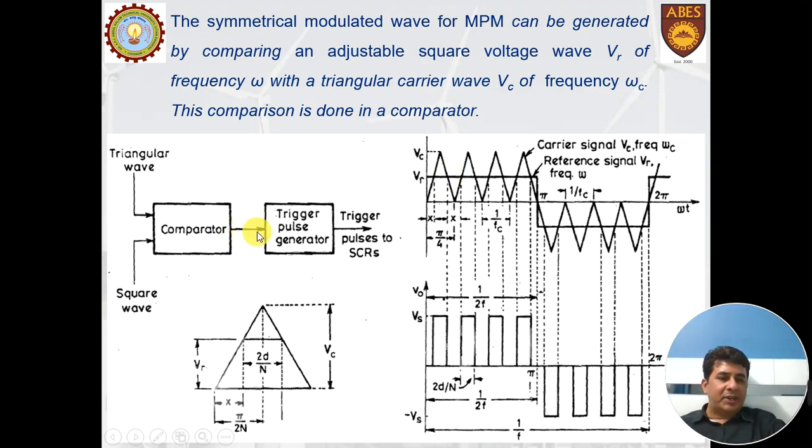At this time the comparator output is low. It sends another pulse, and at this time it is not the triggering pulse, rather it is the time when this thyristor is commutated. Now here the device is commutated, and so the output becomes 0. Now again at the third intersection, this pulse is given to the thyristor. Here it is commutated, then here it is triggered, here it is commutated.